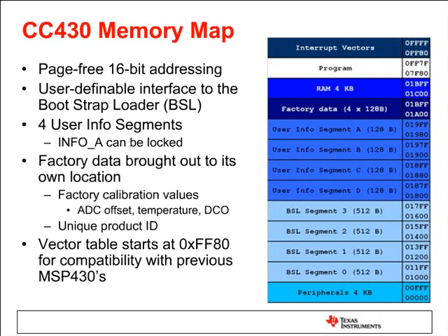But this bootstrap loader is reprogrammable flash. So we intend to provide you a library, and with that library you can select your interface. You can reprogram the interface of the device, which I think is cool. You can reprogram to I2C, you can reprogram to SPI, you can reprogram to whatever frequency of UART you desire, and we have that memory allocated for you, and it's fully reprogrammable. By default, you get a 2-wire timer UART, operating at 9600 BPS.